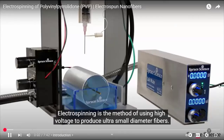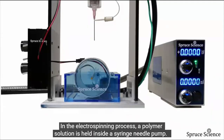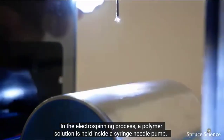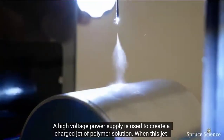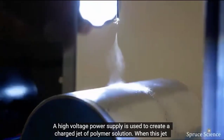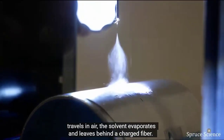Electrospinning is the method of using high voltage to produce ultra-small diameter fibers. In the electrospinning process, a polymer solution is held inside a syringe needle pump. A high voltage power supply is used to create a charged jet of polymer solution. When this jet travels in air, the solvent evaporates and leaves behind a charged fiber.